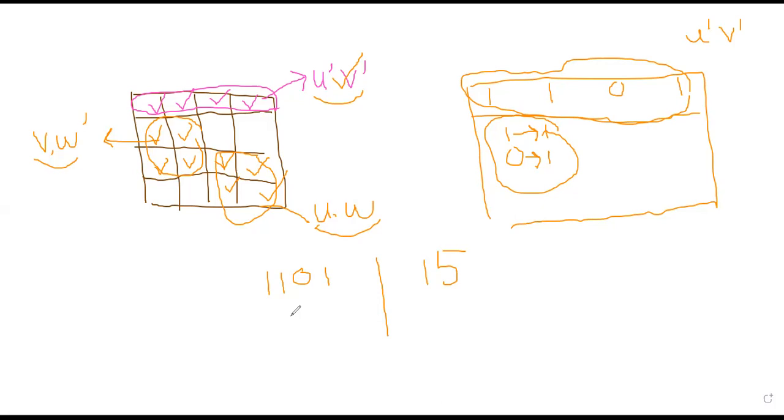Yes. Again, the toggle flip-flop, Abdullah, basically depends on two inputs. First is the T input, and second is the clock input. There are two cases, whether T is one or zero.